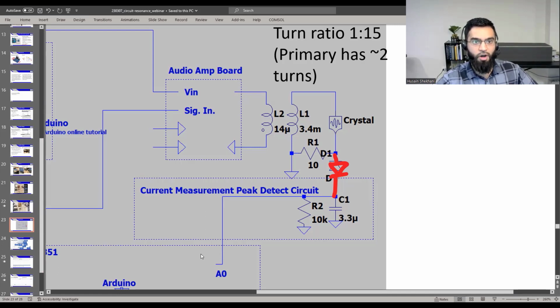I also like to turn off the device and see how fast it drops. If it drops immediately, that's perfect. If it doesn't drop at all, based on the resistor and capacitor value, then I'm concerned.